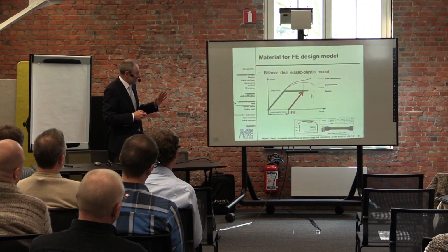So, component-based finite element model, we have to have a look first at the material, then at different connectors, bolts, welds, anchor bolts, and we have there the question of slender plate, and also we are modeling the concrete block. To simplify it, instead of a concrete block, we are using an elastic or Winkler hemisphere, elastic hemisphere.